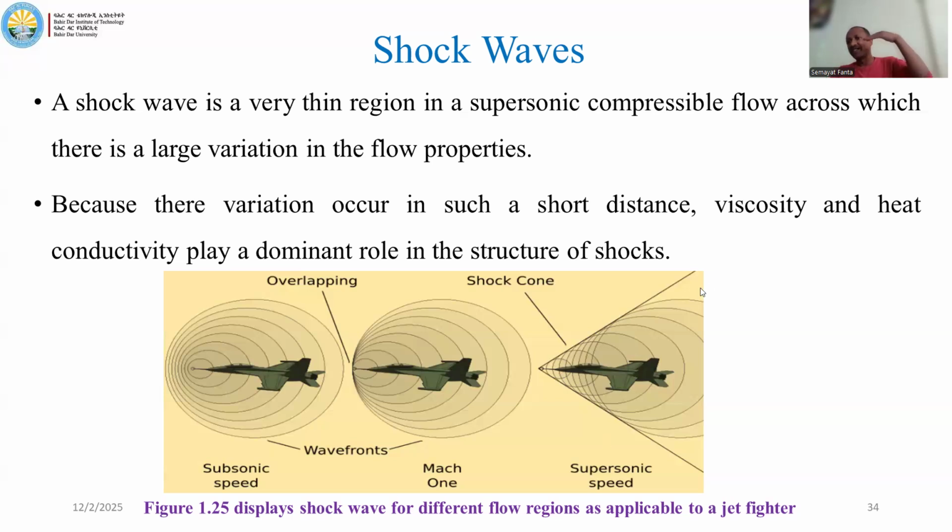For a helicopter, you can hear its sound before you see it. For an aircraft moving at Mach 1, you can observe it just at the top of you. And for an aircraft with Mach greater than 1, you can observe it after it passes you, because the sound speed is less than the speed of that object. That is the logic behind it, and the Mach cone formation is of that kind. What we are hearing is from the formation of the Mach cones. It is just particle disturbance, or pressure disturbance. What we are hearing is the pressure disturbance.